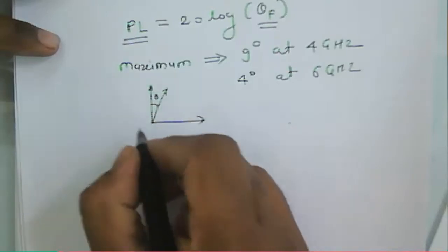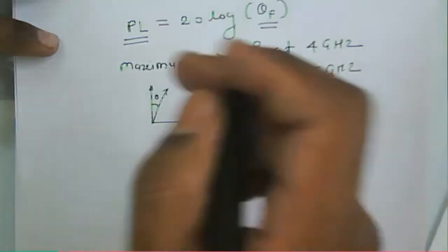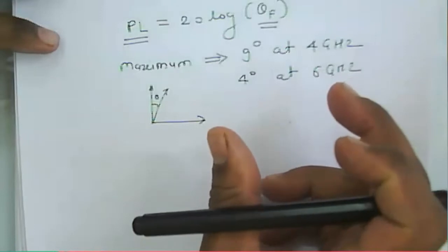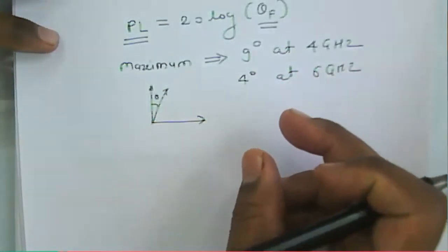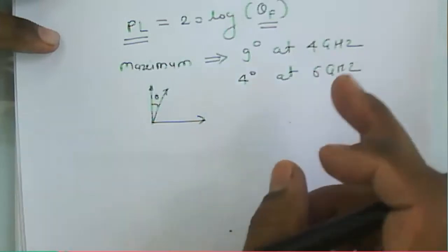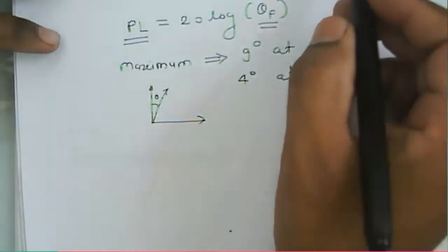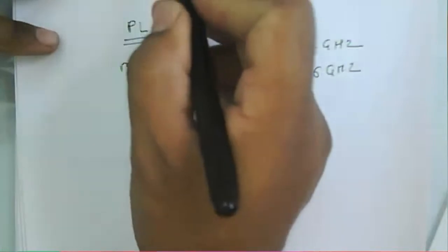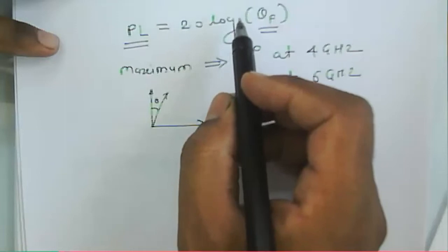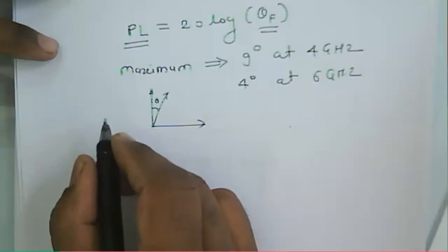But in the case of a left-hand circular wave, or a right-hand circular wave, meaning circular polarization, there will only be a small variation in the angle. This angular shift will occur, and that angular shift will be added to the Faraday rotation, the overall rotation. So that's why we can prefer the left-hand circular polarized wave or the right-hand circular polarized wave.